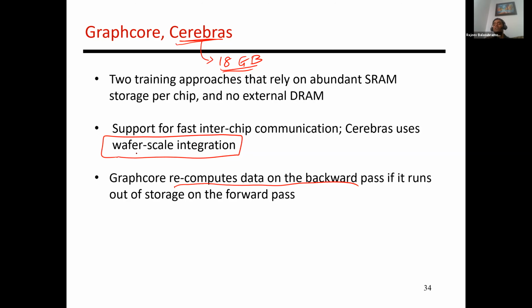because you're anyway going to have to buy a bunch of these chips to do distributed training. And so by keeping the wafer intact, I can have extremely high bandwidth communication between these chips, right? But now they have to deal with cooling, power delivery. They have to deal with the fact that there'll be errors on some of these chips, right? So there are all these engineering issues which they've not fully explained how they address. But I think that's the stuff that they'll figure out over the next few years.